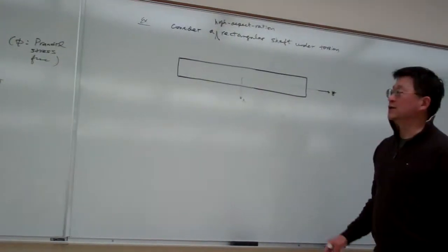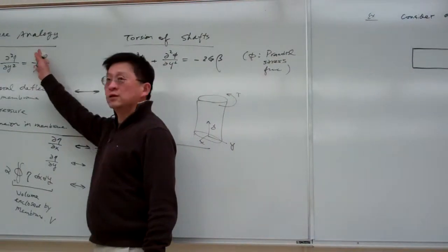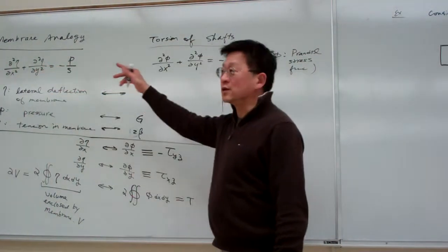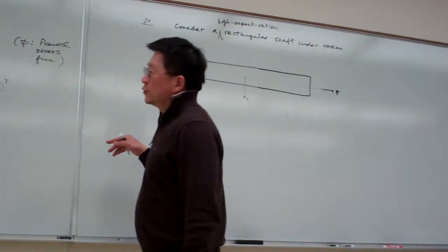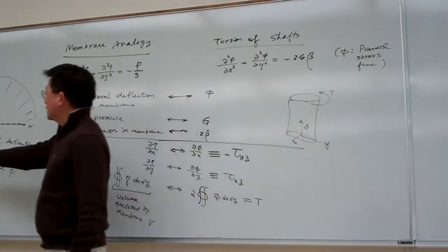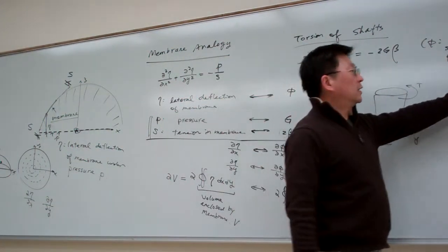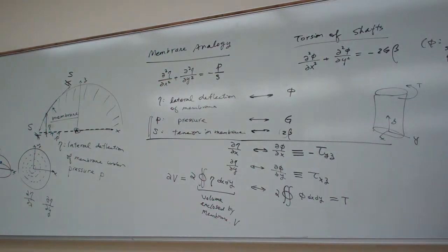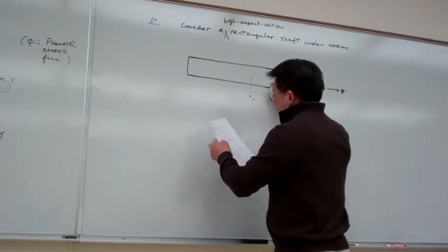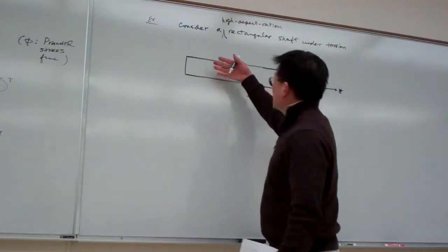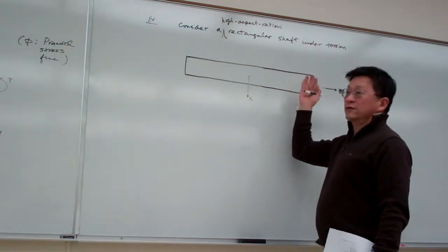And here, let me present the third one, which is again to borrow this advantage. To use this one, we simply mimic the cross section of the shaft with the metal ring. So I'm going to start with the membrane. Assuming this is the metal ring, we put the soap film onto it. So this is the top view. The soap film basically fills up here.